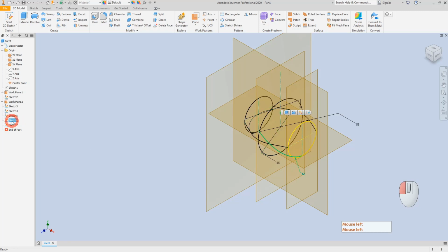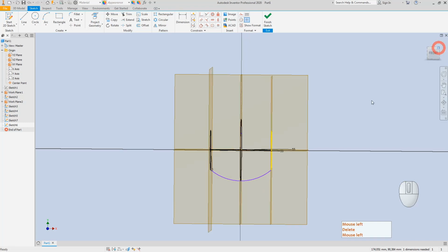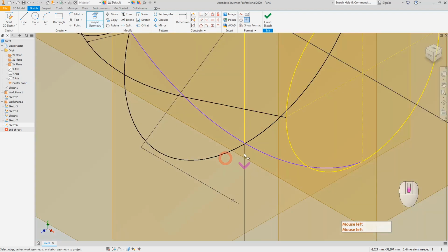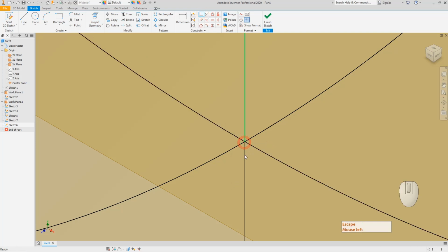For this reason, I will just change the order to see the pathway, or to see our sketch, during our modeling. I will shift my bottom pathway, delete the dimensions, and redefine that relationship by using the projection of the circle and make this curvature pass through the midpoint or endpoint of the line which I'm going to create.